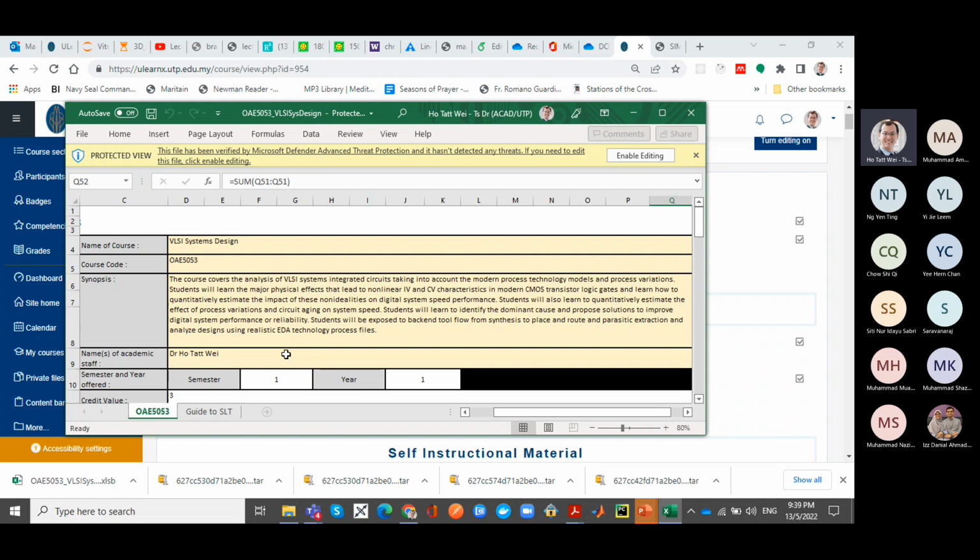Collectively, these are known as the standard cells of a process technology. They are standard logic cells, standard NOT gates, and they come in various forms and sizes. The old style of VLSI looks at how you design one or two of these standard cells and how you lay them out. That's less important nowadays because fabs are now a service. They are no longer in-house. The majority of digital IC engineers don't design the gates in the fabs. They just use them. They design the circuits and then use the gates.